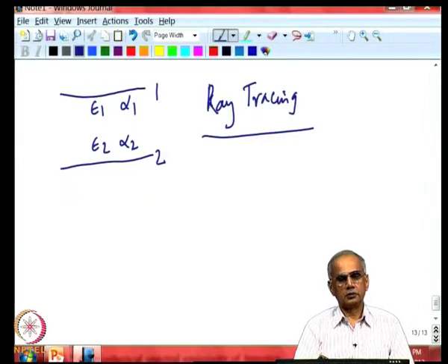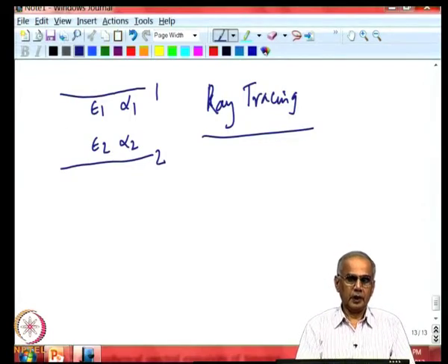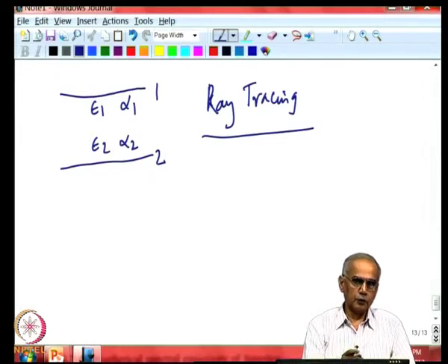You just start with the photon emitted by one surface, keep following the photon as it reflects, and ultimately once it is absorbed, that life of the photon is over, and you count the last place where the photon was absorbed as having gained heat, and then you look at another photon emitted by another surface.